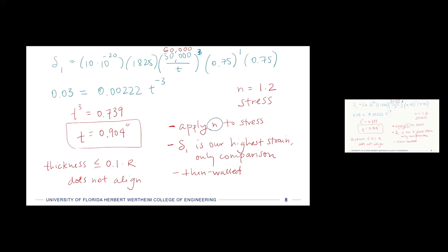And so if we're using our safety factor on our failure criterion for this specific problem, that's the creep strain, right? So you could come over here and divide the allowable creep strain by 1.2, which then drops our allowable creep strain, right? If we do that, however, and we keep all the other assumptions the same, our wall thickness has to increase to compensate for that, right?